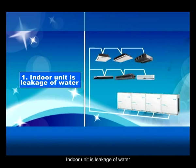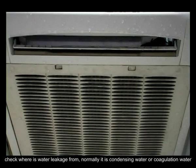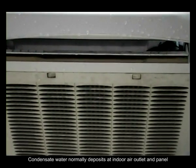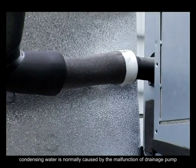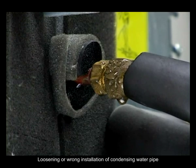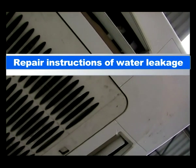Indoor unit water leakage. Check where the water leakage is from, normally condensing water or coagulation water. Condensate water normally deposits at the indoor air outlet and panel. Condensing water is normally caused by a malfunction of the drainage pump, or a loosened or wrongly installed condensing water pipe. Repair instructions for water leakage.